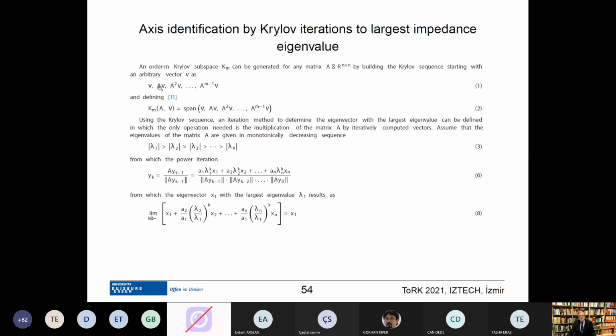But it is very difficult to measure this matrix or a stiffness matrix because it's 6 times 6 and you have many effects that are mixing. So the idea was to not compute this matrix, but let the body do this multiplication, just by applying a force and looking at the resulting twist, where actually it's a wrench, force and moment. Then we apply this twist again as a wrench, of course scaled. And then look at the twist, and then apply this twist again as a force wrench, and repeat that. By doing this, we are actually carrying out this power iteration on the body itself.